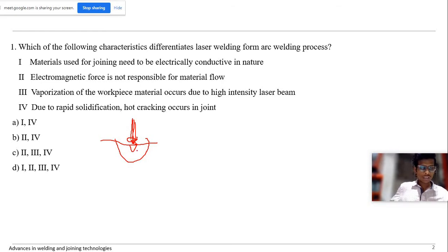Once it is directed towards the molten pool and is getting melted, its absorption will be more compared to the corresponding liquid metal. So this will get spread and built, so the keyhole is happening, and we are getting keyhole mode. For that, the temperature generated should be more than the vaporization temperature. Once it is generated, because of the vapor pressure, this keyhole is maintained, and surrounding that there will be liquid molten metal. Once it moves forward, this gets filled by the surrounding liquid media, and welding proceeds further.